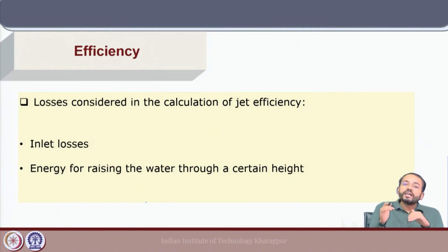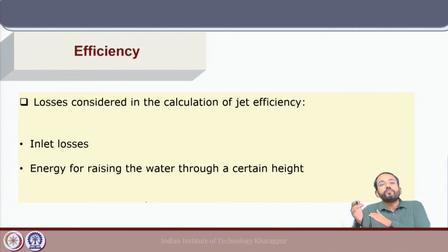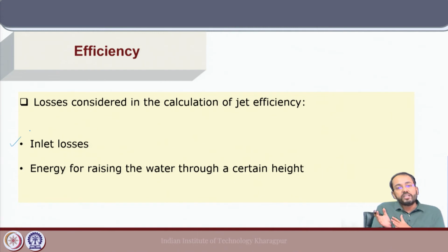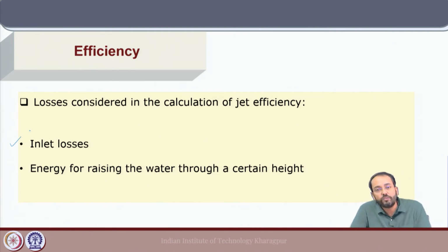So, the location of the inlet at the particular region of the ship hull below it is very important in defining the losses that will be incurred in a water jet system, which are the inlet losses. And the boundary layer on the ship hull at the location of the inlet will play an important role in the inlet losses, which will impact the water jet efficiency.